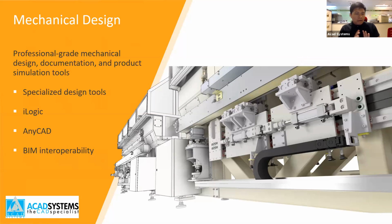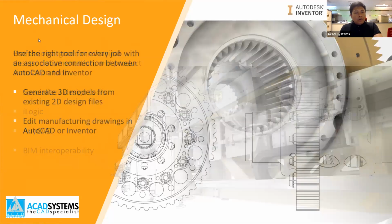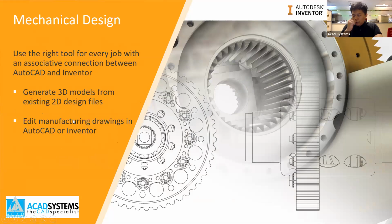Okay, so parametric modeling is very basic before you start design automation. For example, if you plan to go with iLogic later, you need to create parametric modeling first before you go with iLogic. With Design Mechanical, after you're done with your 3D parametric model, you can also automatically generate your 2D drawing. The dimensions will follow together and the scale you can set later on.